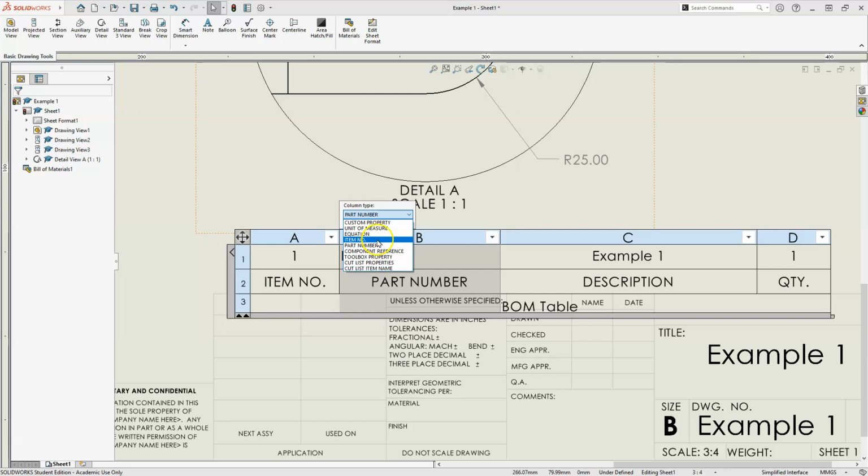And let's make sure I did do that one. Okay. That's not the right part number one there. Oh, custom properties, that's where I need to go. I forgot that I did make it a custom property. And then if I go to part number, you're going to see the 1, 2, 3, 4, 5, 6 come up. And then underneath the description is here.